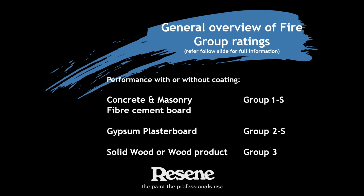These are the group ratings from the code. Group 1 is concrete and masonry, fibre cement board. Group 2, plasterboard. Group 3 is your timber area. Just an interesting factoid: our friends at Winstone Wallboards' GIB board actually tests into Group 1. What we're looking at on screen is the generic group ratings from the building code.